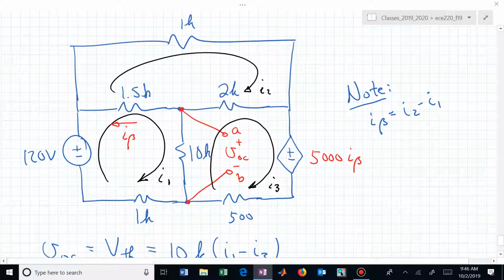When your circuit is non-planar. You have to have a planar circuit. You have to have these meshes in order to do mesh current analysis. Node voltage analysis always works. I've found that traditionally students prefer mesh current analysis. It's easier. I'm sorry, I shouldn't say that. It just appears more straightforward to the majority of students. But you don't have to use it, and you need to be very comfortable with doing node voltage analysis, writing KCL equations. Here you're writing KVL equations.